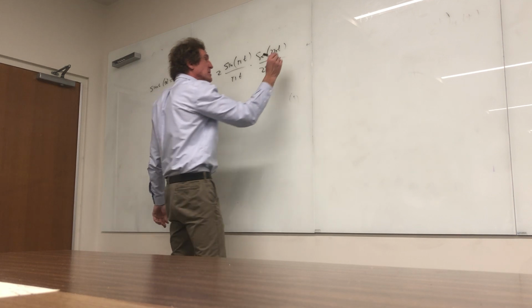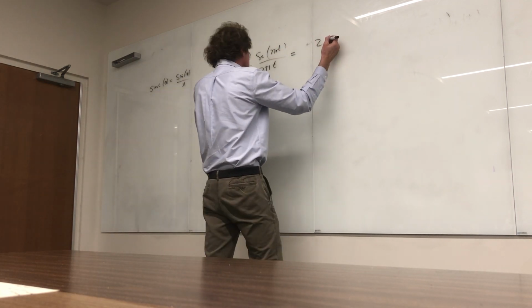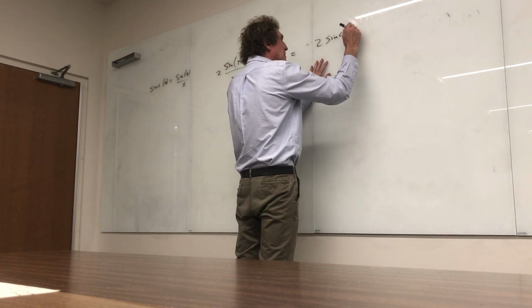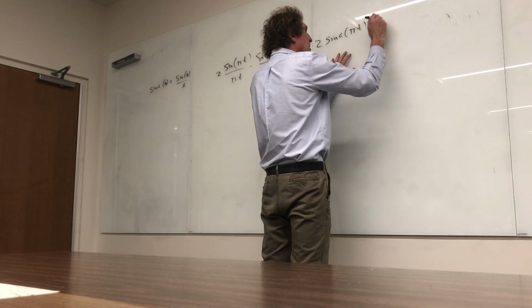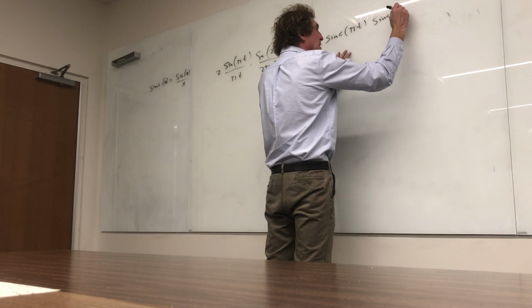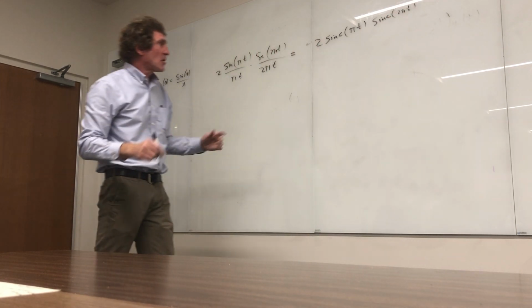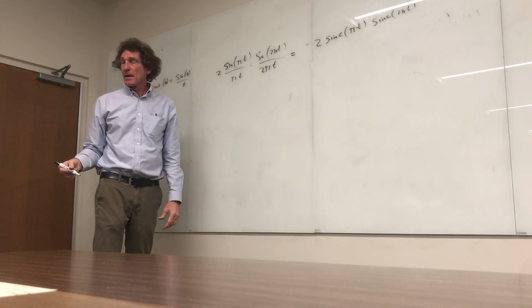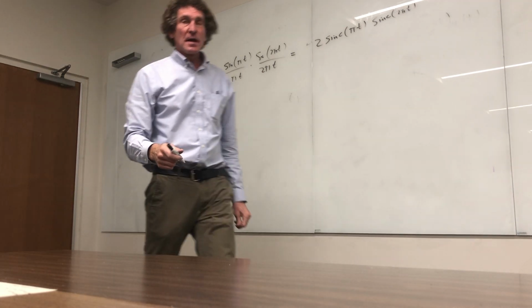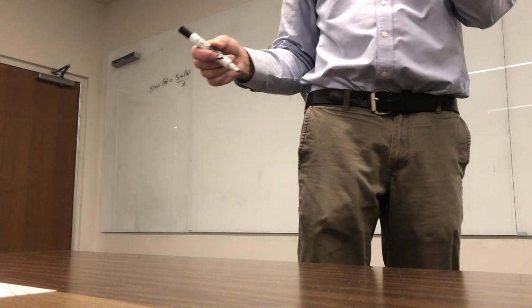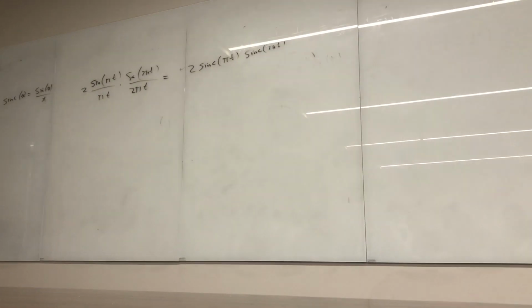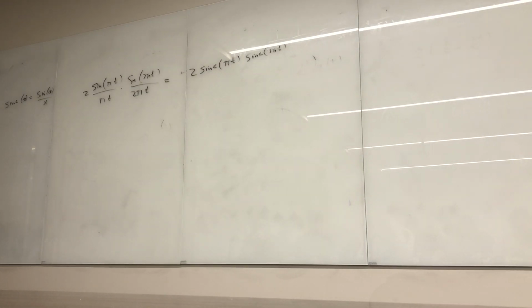So now I'm going to render this as simply 2 times the sinc of pi t times the sinc of 2 pi t. I want to make sure that's the function. You can call it anything you want, but that's it. Do you agree? Now we use duality at this point to get where we're going. We're going to have to do convolution, but duality is the key thing on this. So let me take you through this. Anytime I think of a sinc function, I think in the other domain, it's a pulse function. Let me just take you through it.